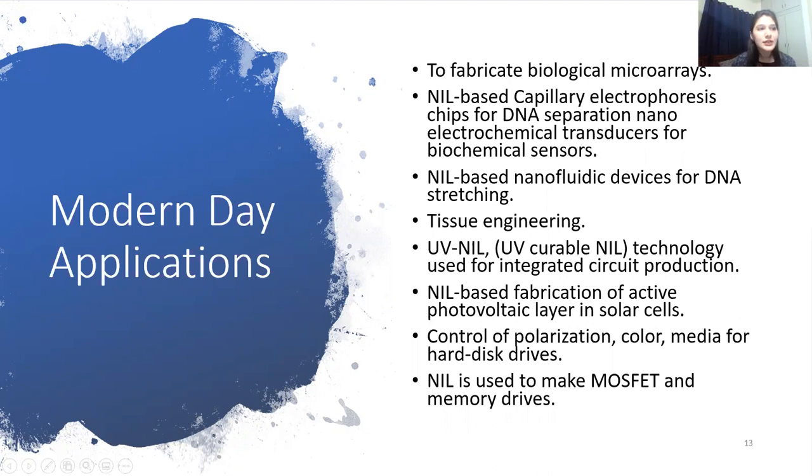Nanoimprint lithography is a parallel patterning method to fabricate biological microarrays, which will boost biotech devices' sensitivity and accuracy. Examples include NIL-based capillary electrophoresis tests for DNA separation and nano-electrochemical transducers for biochemical sensors. 10 nanometer nanofluidic channels were developed using NIL technology and were used for DNA testing.